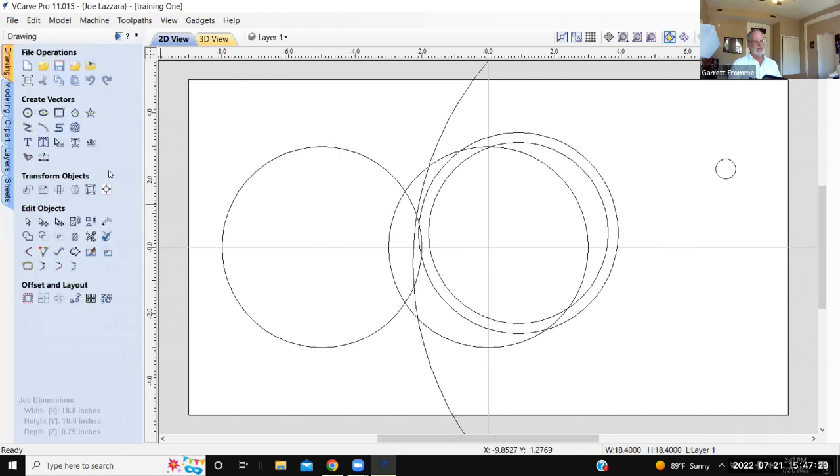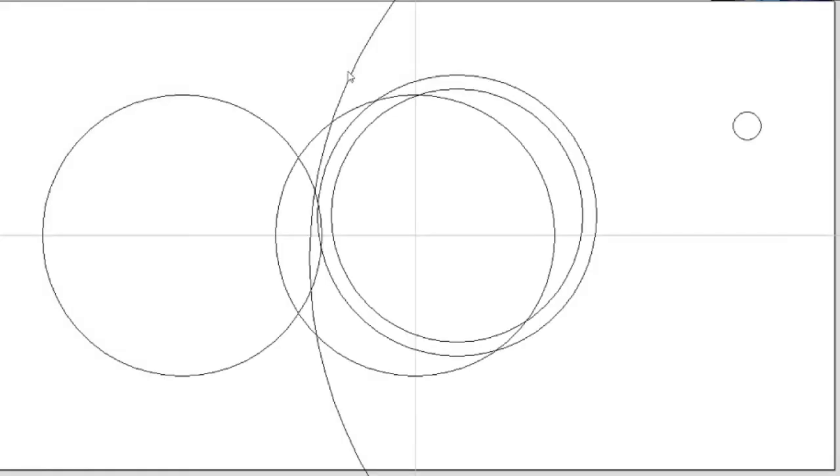Okay. Now select the big circle. I'm going to teach you how to select these things. I'm going to come in first. The first way to select items is by hovering your mouse directly on top of it and clicking once, and it's selected. Okay. The other way you can do it is by coming from right to left, very specific. As long as that box that I've created touches that circle, it's going to select it. Okay, that's from right to left.